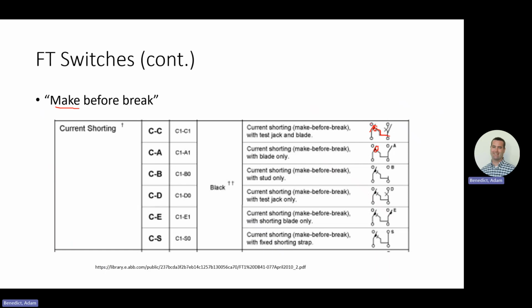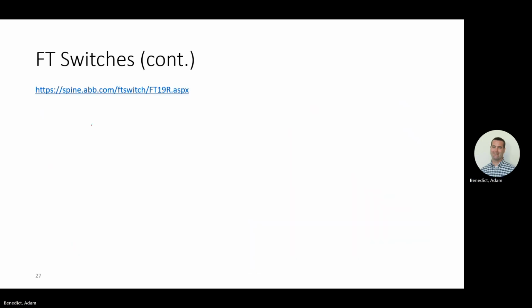So if you were to open it, before it leaves this terminal, it's making contact here, shorting out where your CT is. Let me draw it down here. So you would have your CT connected down here. And then as this opens, it makes contact, shorting across, before it leaves that terminal. Fun fact.